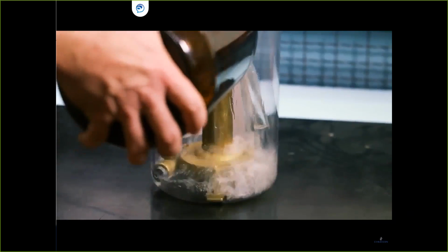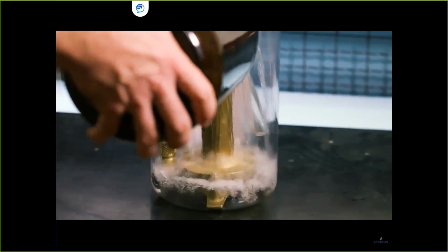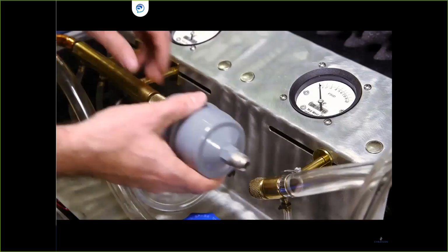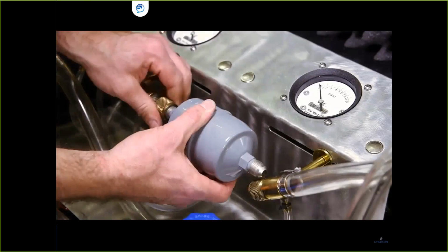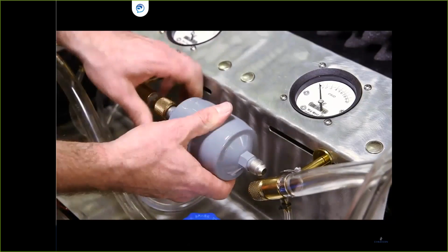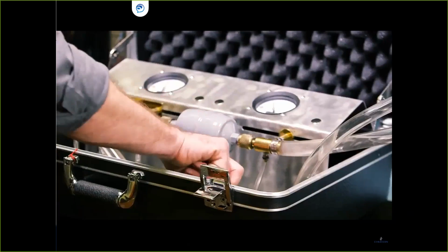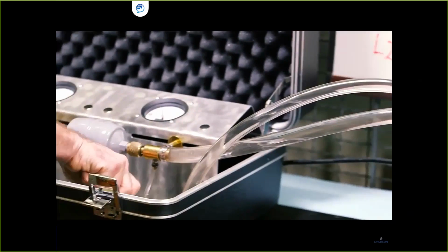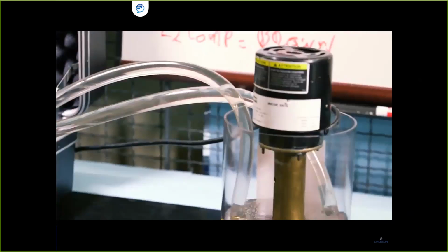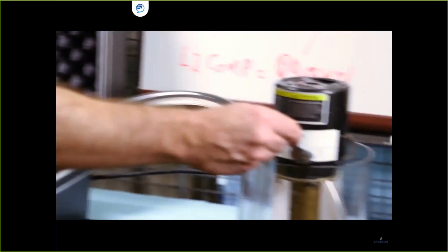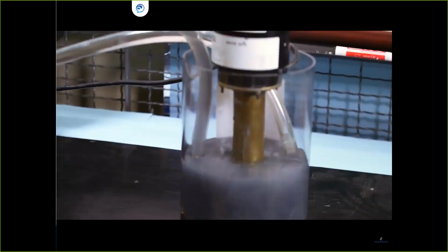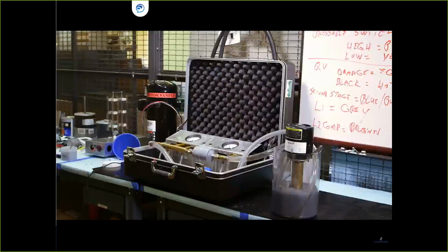By filling the receiver tank with refrigerant in this closed-loop system, we simulate the conditions present in an air conditioning or refrigeration system. First, we'll install a competitor's solid core filter dryer. Starting up the system, you'll see the liquid refrigerant entering the dryer, passing through it, and then being recycled and pumped back through the system. We'll now add roughly 5 grams of solid contaminant into the system. As you can see, the refrigerant is pretty dirty.